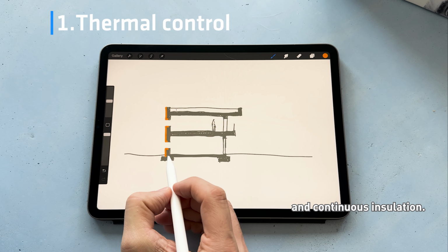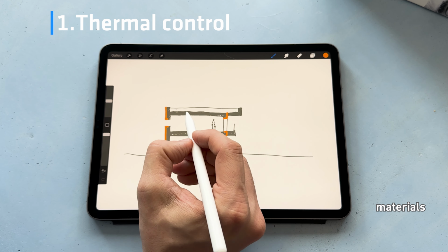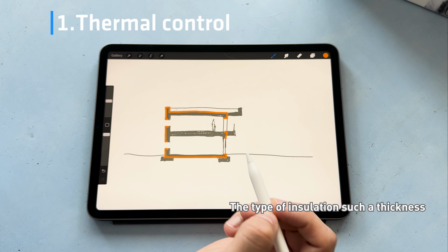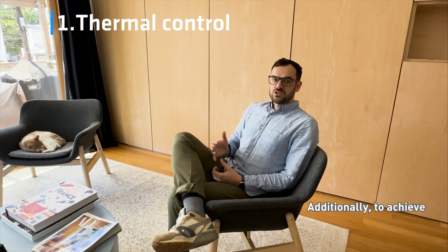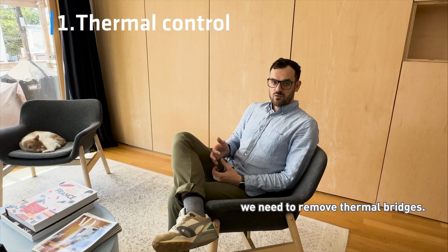In fact, it is the first item most people think of when mentioning passive house. Adding a thick layer of insulation materials helps reduce large energy exchanges. The type of insulation, such as the thickness, depends in part on the project's climate zone. Additionally, to achieve greater thermal control, we need to remove thermal bridges.